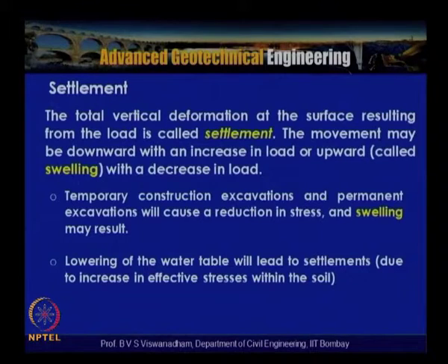The movement may be downward with an increase in load, or upward with a decrease in the load. When the load is decreasing, there is a possibility that swelling or heaving can take place. The downward movement is called settlement.